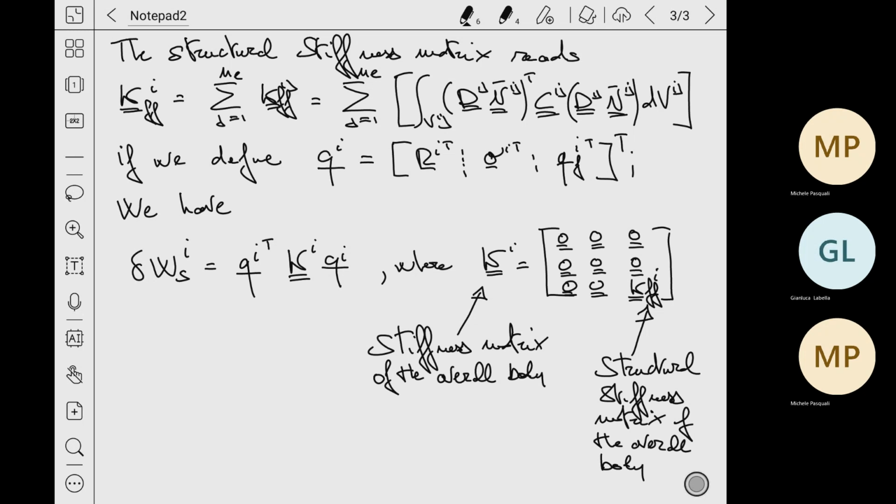So you see now that in this case, given the limiting assumptions that we have made, the stiffness matrix is a constant matrix. You see, it's just made of elastic constants. N is a constant matrix because of the mode shapes, but when you integrate them, they basically give you a constant value. D, the matrix D, is a matrix of derivatives.